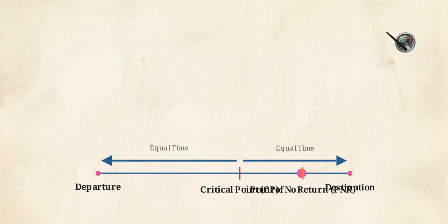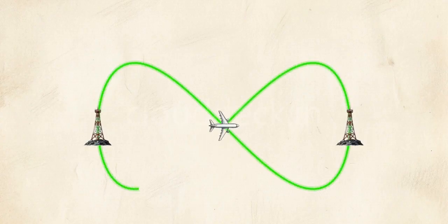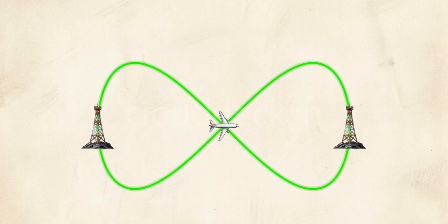on its fuel endurance. To verify their dead-reckoned position, aircraft use an automatic direction finder to track ground-based non-directional beacons. A basic loop aerial receives the radio signal in a figure-8 pattern, which tells the pilot the line of the station, but creates a dangerous 180-degree ambiguity on whether it is ahead or behind them.